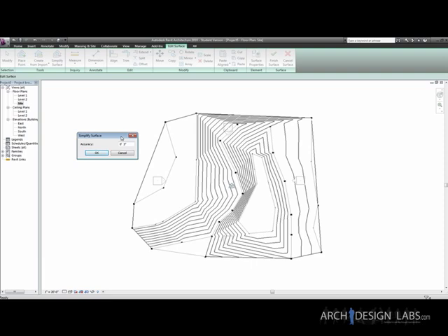So depending on your project size, you may want to change the accuracy of the topo surface, because it will copy those lines exactly. So if you have crazy lines going like this, and it has 1,000,000 points per line, it starts to become too large of a file and too complex for just a simple house you're trying to put on this landscape. So you can adjust that here.